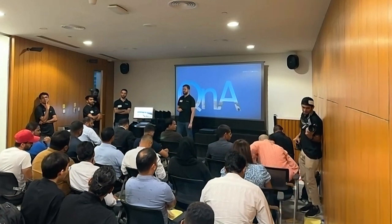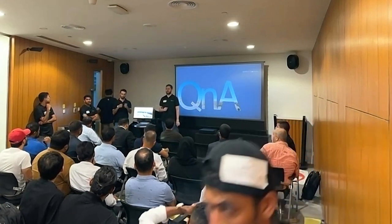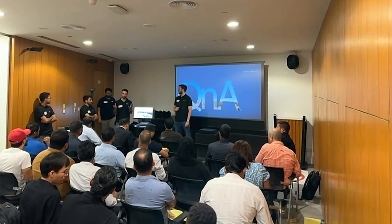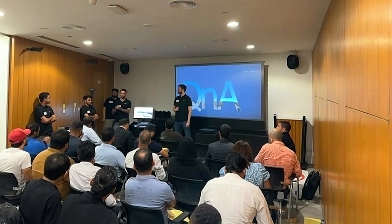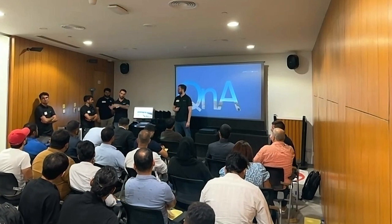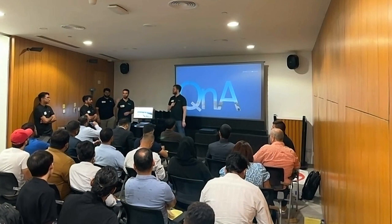First, you cannot connect 2 benchmarks to one drone. What you will do is make your benchmarks as a network. So later, when you process this benchmark as a network, whatever you connect from the beginning, first benchmark to drone, later disconnect and connect to second benchmark, third benchmark. You know, a corridor maybe you will have 10 benchmarks. You need to connect each section alone. Bandwidth is a limitation. My advice would be look at 2 drones.